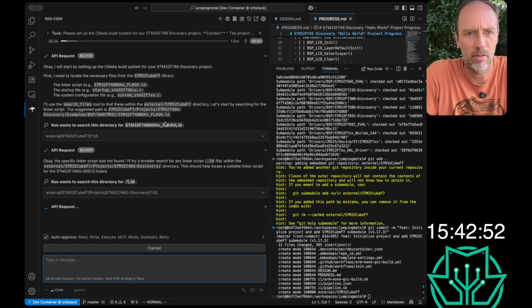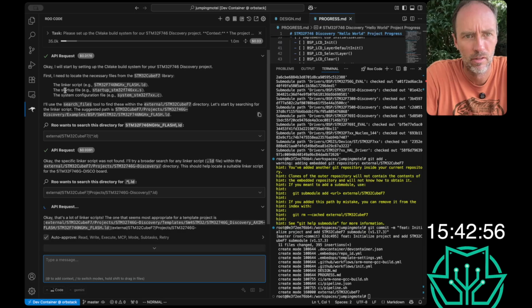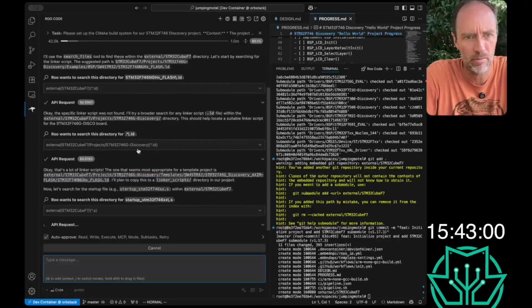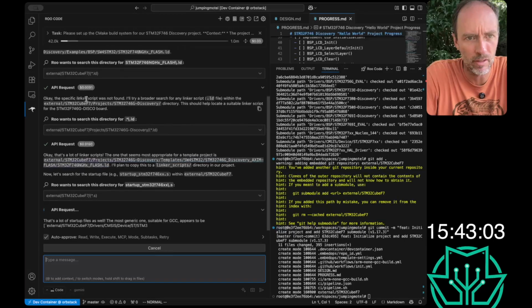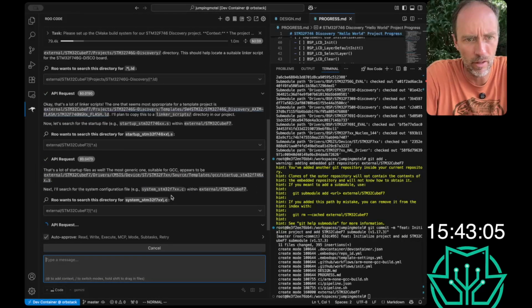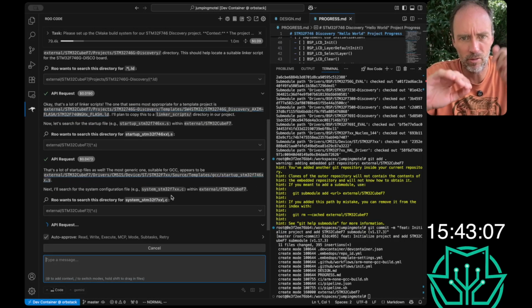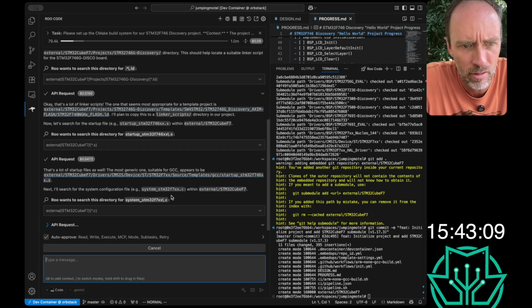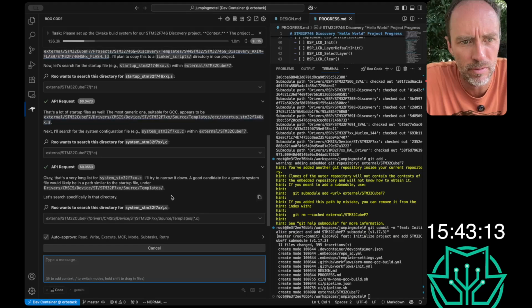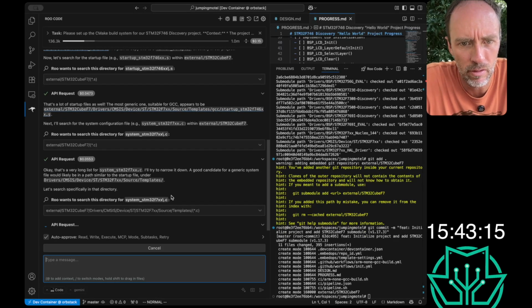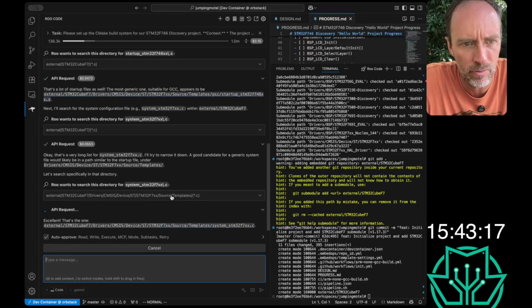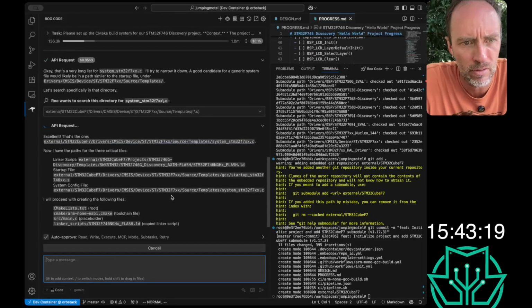All right, started the CMake build system for this project. Should be a linker script. Startup file, yep. System configuration, okay. Gonna look for those in that there. There's a lot of startup files. All right, the most generic one suitable for GCC is there. Okay. A lot of linker scripts. Long list. Try to narrow it down to a good candidate for generic templates.